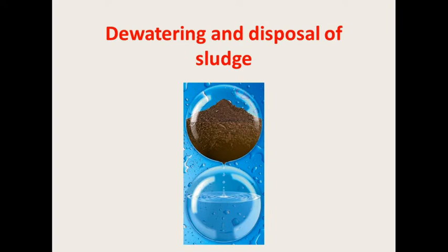It consists of a filter cylinder composed of fixed rings and moving rings, located between the fixed rings and the screw shaft. The moving rings are pushed up and down by the screw shaft, resulting in clean solids coming out from the gaps between the fixed rings continuously. So this process is called sludge thickening.